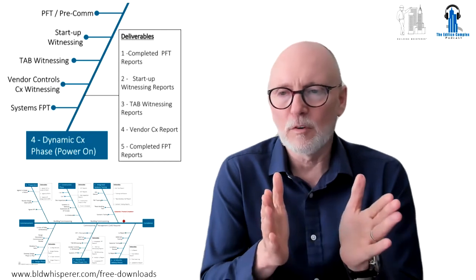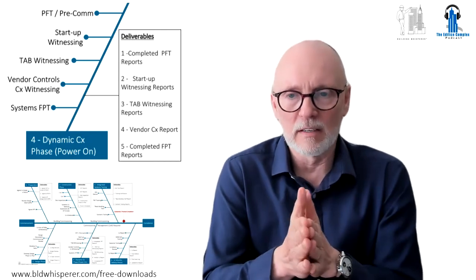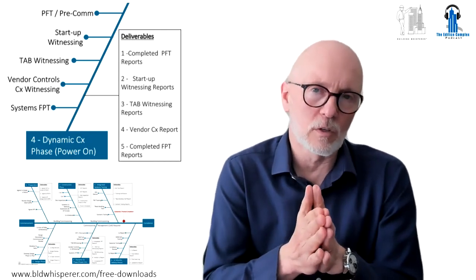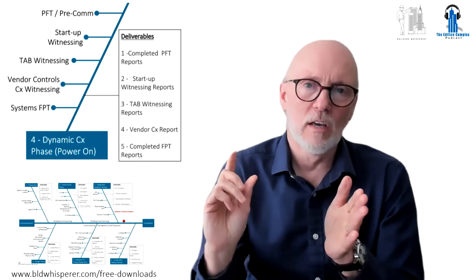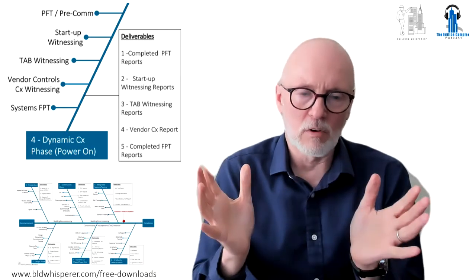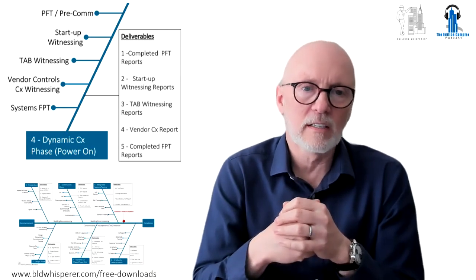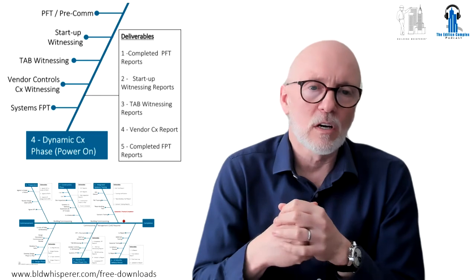I'm just so fed up of trying to commission systems without them in. If you want to commission a control system, you have to test it from device all the way back to controls head end with the BMS graphic to make sure everything is correct. And then we get on to task number 5.